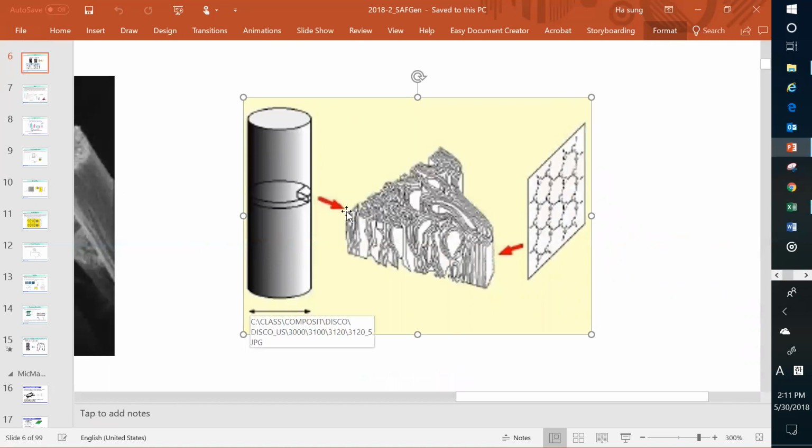Okay, but glass fiber, as you can see, is pretty much isotropic. So glass fiber has the same material property everywhere, isotropic. But carbon fiber itself is anisotropic. You can imagine this kind of layer. It's like a graphene layer rolled like a cigarette rolling.